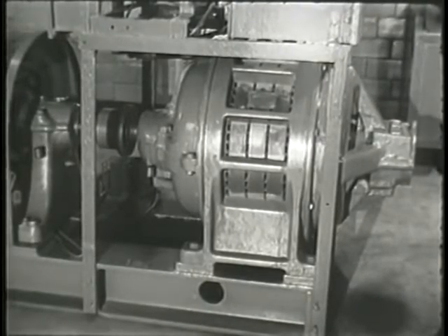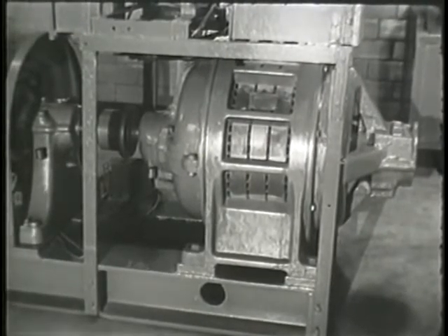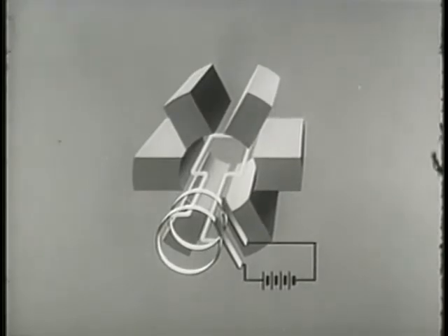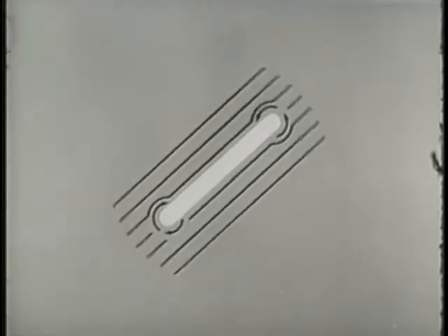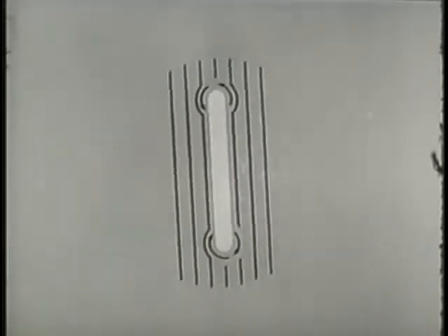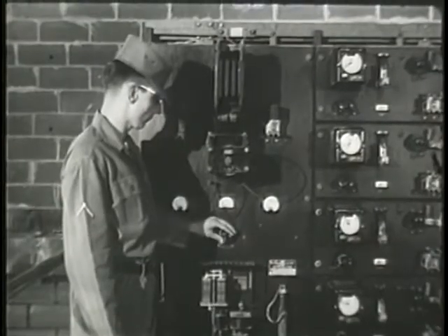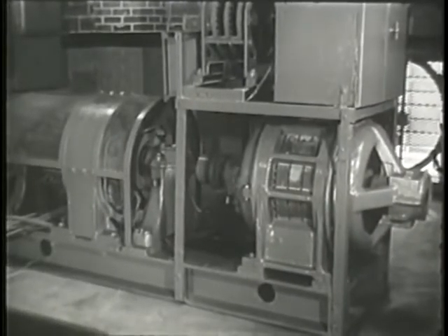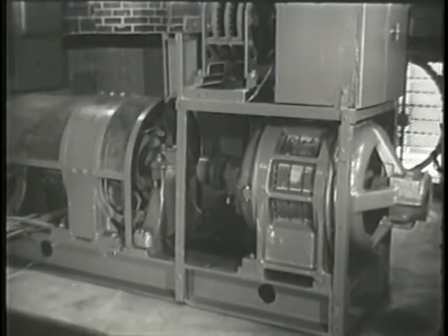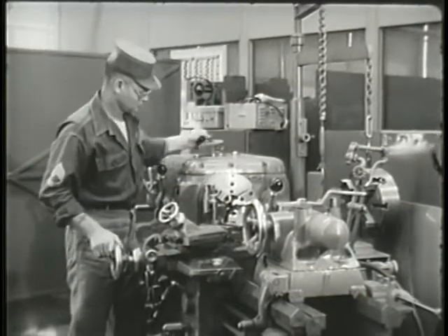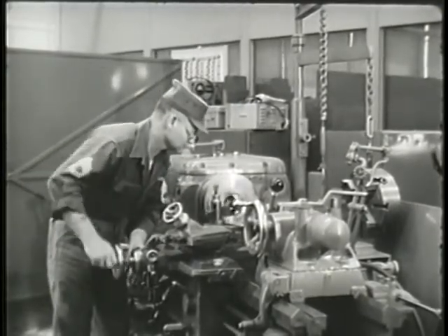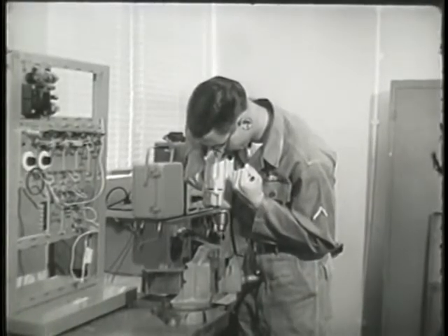In synchronous motors, there is no need for relative motion. The EMF needed for the rotor is supplied from an outside DC source. Here, the rotor and the revolving field rotate at the same speed. AC rotating electrical equipment is the most practical for a multitude of uses. Knowledge of the principles of alternating current is essential to intelligent operation of such equipment.